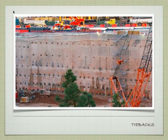Generally, to get the tiebacks into the ground, how many would you use? It'll be a long drill like that. You saw the core drill, right? That a few slides back about taking out that core sample. Same concept. It's going to be a really long drill that's on an angle, right? That drills through that slurry wall and all the way into the earth. Then you insert your cables and you inject your grout. Then there is a special machine that comes and tensions the cables and slides the plate on.